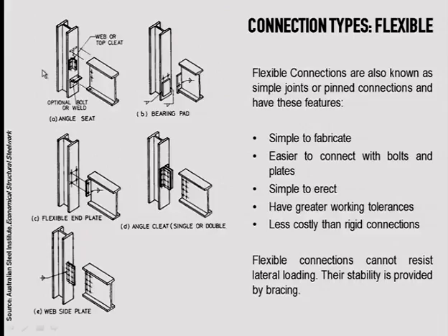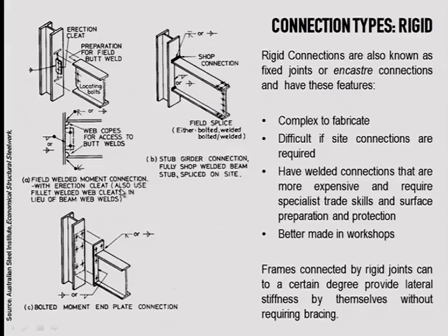And most of the times when we use bolts, the connections are flexible, apart from a few cases. And I've just pasted here a few details for you, and also the same for rigid connections, which can be bolted, but generally done with these plates that are able to transfer bending moment in all the locations, and in other cases we weld it.